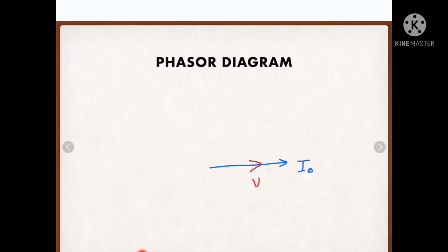Now as we know, in the series circuit we have altogether 4 voltages. One voltage is the supply voltage, other we have the voltage across the inductor, that is represented by VL. Then we have one more voltage across the capacitor, that is represented by VC. And in this resonance VC is equal to VL, and in the phasor diagram we can see that both are in opposite direction, so they will cancel out each other.